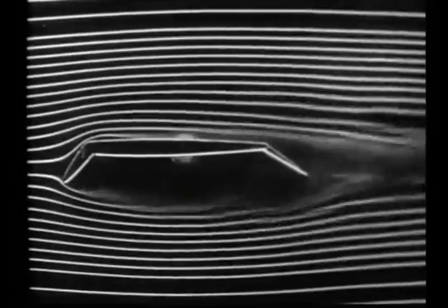So far, we have seen various types of control systems. In applying them, many practical factors must be considered. Typical of these is the possibility of inducing a second separation while attempting to control the first one. Both the leading edge and the trailing edge flap of this thin profile are deflected. Because of severe pressure gradients, the flow is separating from the lower surface of the leading edge, from the break of the leading edge flap, and from the break of the trailing edge flap.